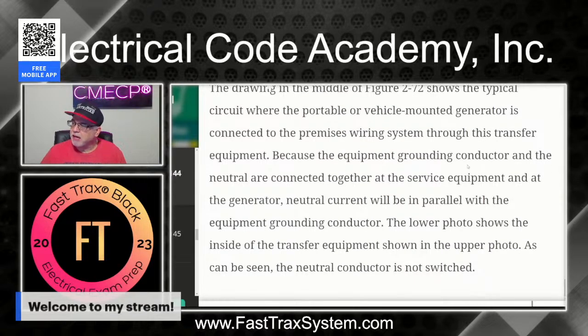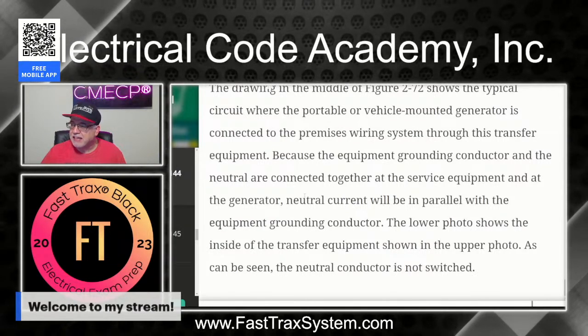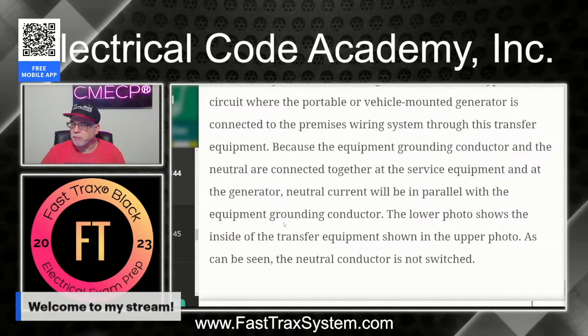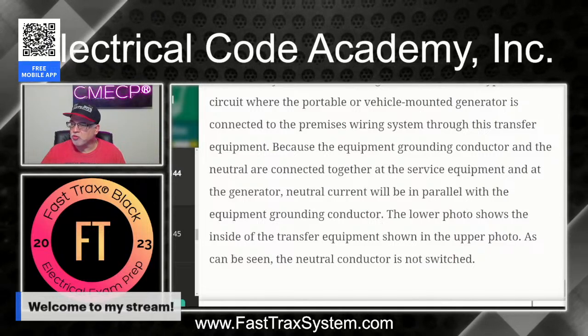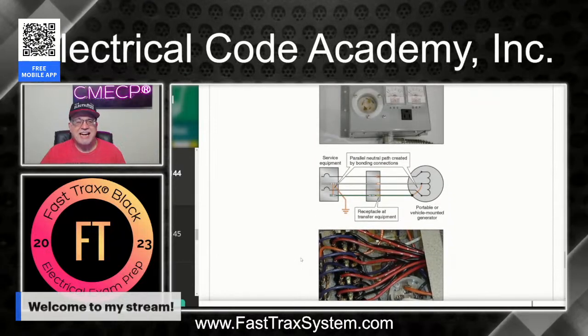Because the equipment grounding conductor and the neutral are connected together at the service and at the generator, neutral current will be in parallel with the equipment grounding conductor. Okay? So the lower picture shows the inside of the transfer equipment shown in the upper photo. As can be seen, the neutral connection is not switched. That is a serious hazard.